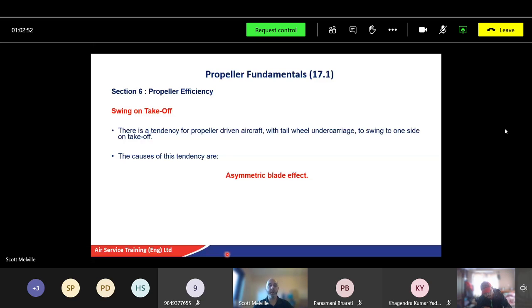So we've looked at asymmetric airfoils and symmetrical airfoils. Now, asymmetric has a slightly larger camber than others. Because of the wind shape that's coming over from the propellers, we get what's called asymmetric blade effect, because the propeller blades are asymmetrical. They're not symmetrical because they wouldn't give you much lift. Then there's torque reaction, the actual torque of the aircraft and the rotation of the engine. And the slipstream effect, as I say, as the air comes back, corkscrewing back, twists over itself and causes a few complications. And good old gyroscopic effect as well, from back to your physics days.